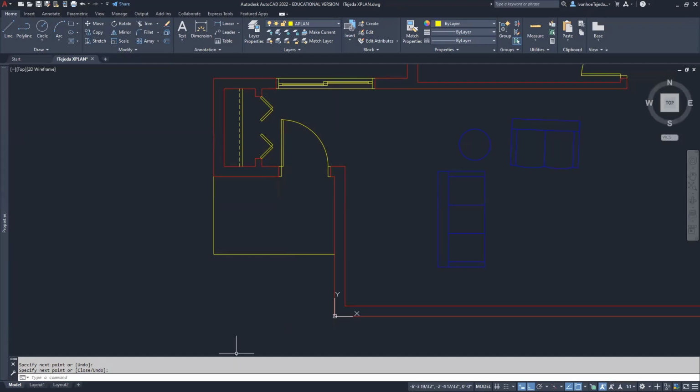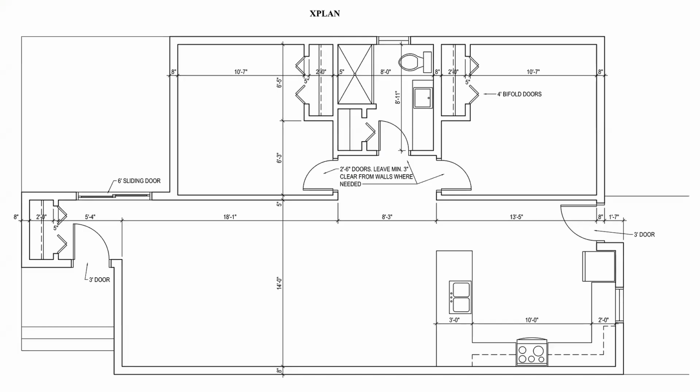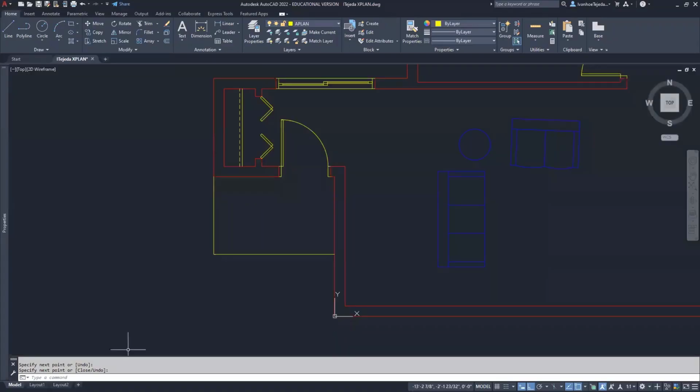And I have, if I look at my drawing, a total of 2 steps and then 3 lines. Each one of the lines represents what we call a riser, and that's the vertical step up. What I see in between those 3 lines, those are the treads. So let me go ahead and draw those in, and they're typically anywhere from 11 to 12 inches, and we'll make ours 12 inches. 2 steps at 12 inches.